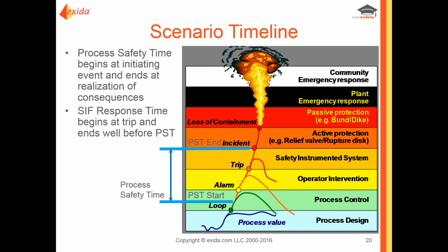The SIF response time begins at the trip and ends well before the process safety time. So it starts at the trip. You want it to end well before the process safety time so we can give time for the dynamics of the process to move forward. But we need to anchor this somehow.